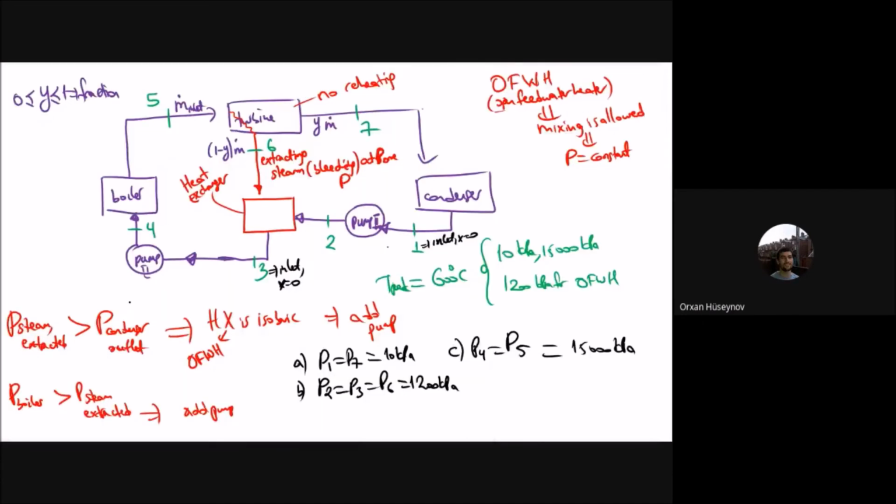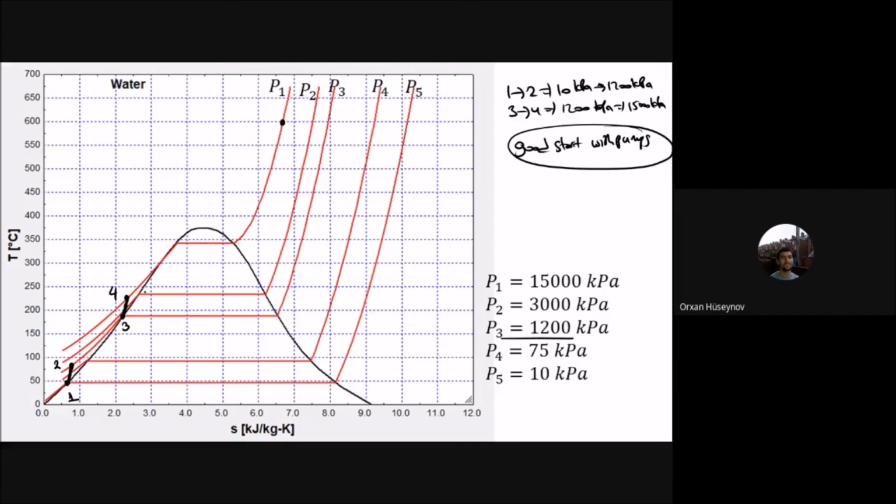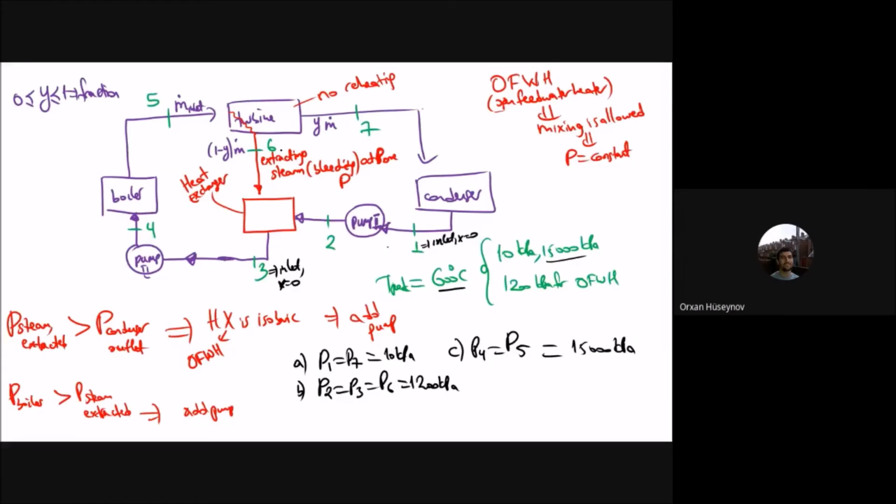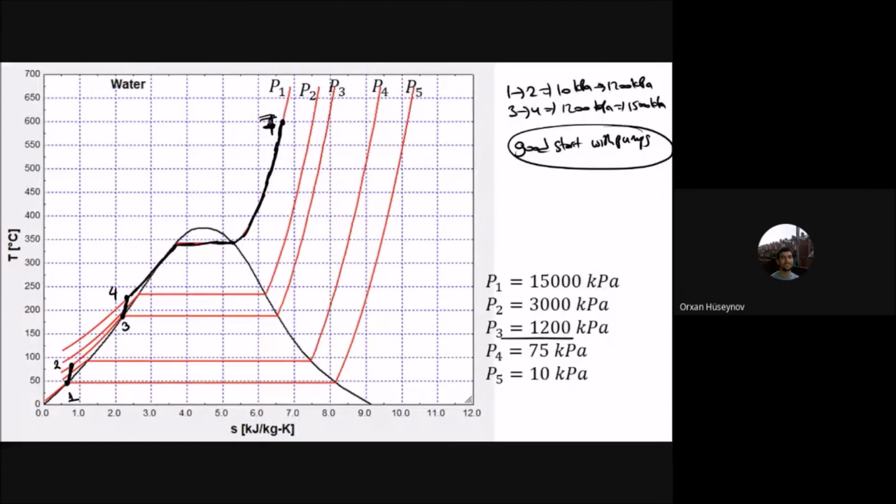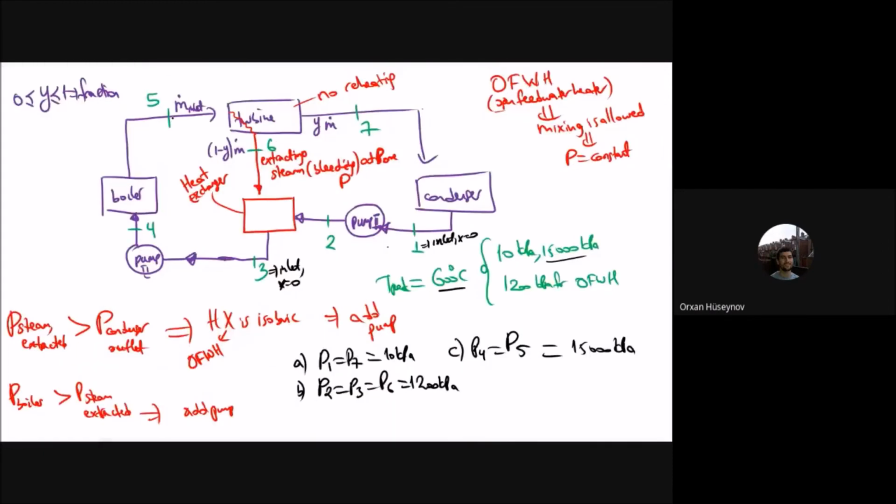And then from that, 4 to 5, you have the boiler with a peak temperature of 600 degrees Celsius and with that pressure. So I will be here, with the boiler part. Let me do that. Actually, this is the boiler outlet. This is point 5. So from this point 5, which is the turbine inlet, that one drops to a value of